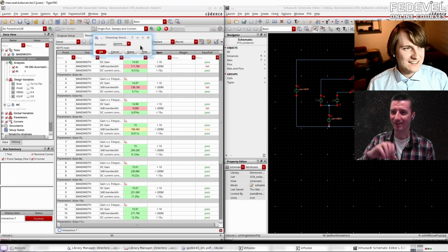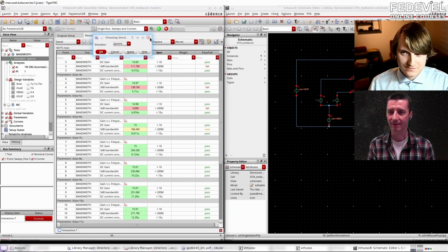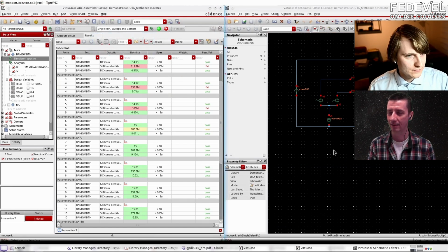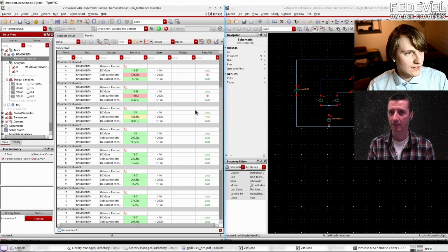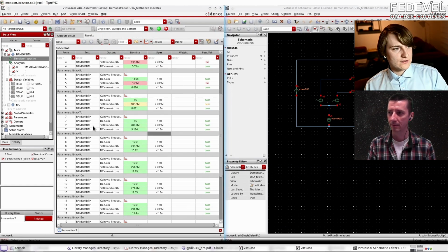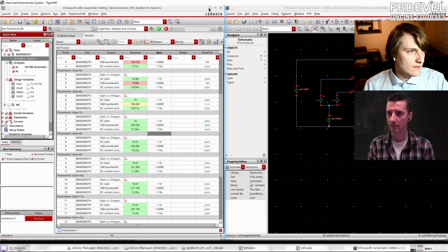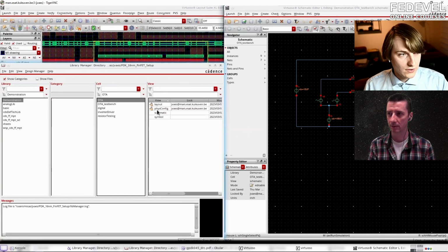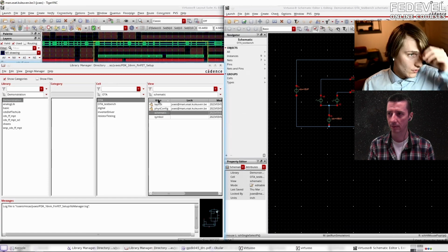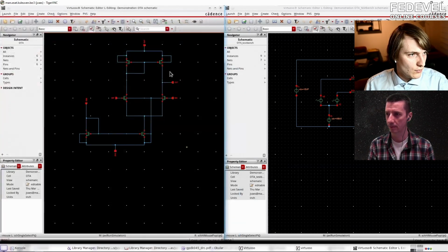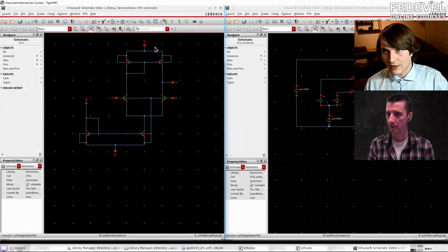Okay. Now let's continue in this. I'm very curious. So we have the schematic, and what do you do next? Okay, so in this case, I've now tested my cell here, and for example, I see that if the bias current here is high enough, then I meet all of my specifications. That's good. So now what I would do is go into layout. So similar to a PCB, right? You have your schematic here with your cells, but now you actually need to do the routing.